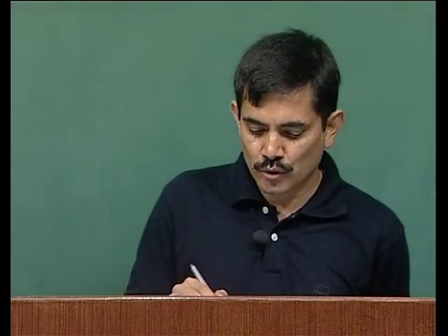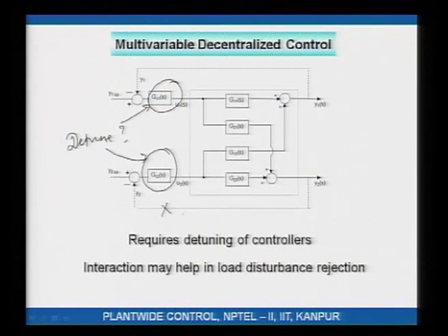Okay. So, in such situations what you do is you switch off this loop, that means the feedback loop connection is not made. Tune this loop individually. Where you desire tight control, that loop is tuned individually with the other loop off. Once this loop has been tuned, you will get a very fast and snappy response in y1. Okay. To tune the other loop, keep this loop on and then tune this second loop.